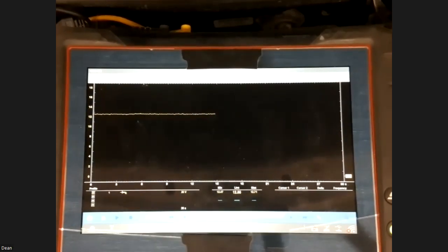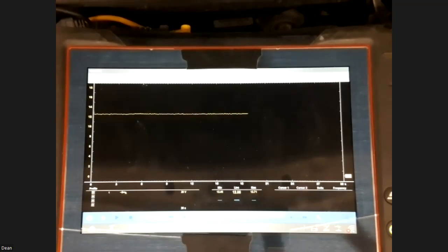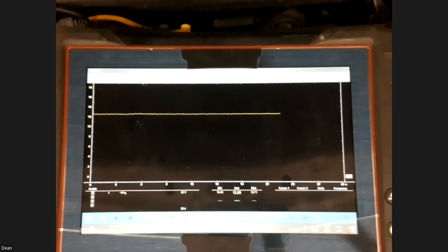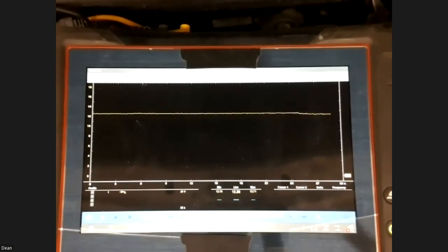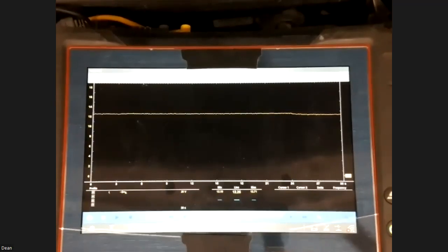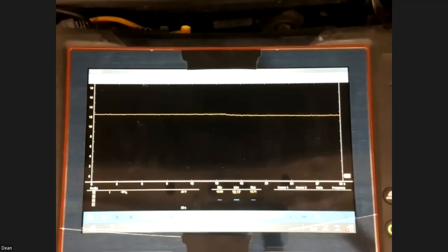Now let's go over to the ignition quickly and see if we can start this thing up and see what happens to the voltages that are on the screen, and I'll go over that quickly. You should be seeing the battery voltages dropping already. So what we're going to be doing to do a proper battery test in vehicles today, what you're going to do is you're going to crank it, make sure that's not going to fall, make sure there's no leads in front of anything.